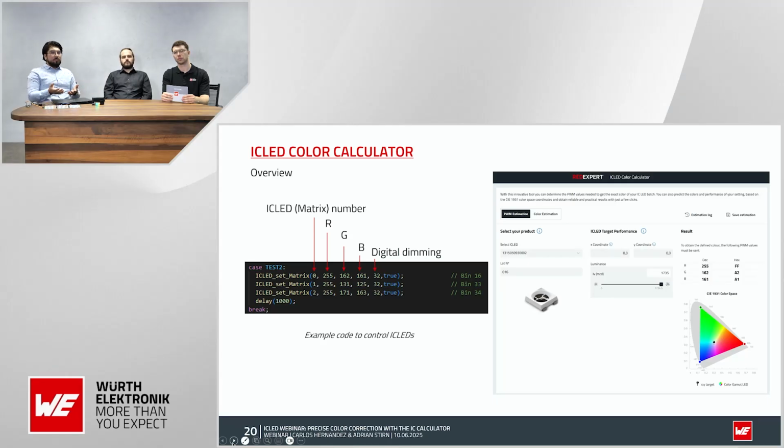In general, we're talking about semiconductors, okay, and it's not possible to have a one-to-one creation from today to tomorrow. So there's going to be differences. The color, the intensity, the characteristics of the LED of every single chip are going to be different. Doesn't mean that we have completely different colors, or that I cannot achieve whatever I want. It's rather in the production, where all the LEDs are going to be measured optically